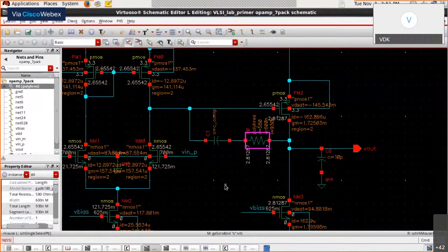So to minimize this coupling effect, whatever change in voltage occurs at the first terminal of C1, if a large chunk of it is dropped across a resistance, so that the change in voltage across C1 per se is minimized, then our job of minimizing coupling is taken care of. And that is exactly what we end up doing by connecting a zero nulling resistance in series with C1.